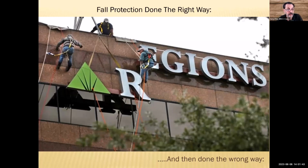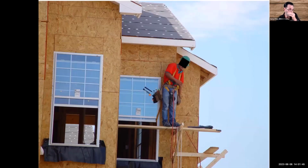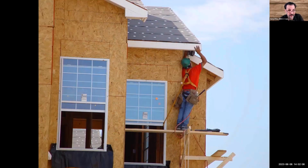But anyways, here, this is a much worse situation. He is tied off, and that's better than what you sometimes have on residential sites. But of course, his plank scaffolding system, OSHA would freak out about. But you see what he's tied off to. He's tied off to something inside the house, underneath and inside, going in that window. And this picture shows it better. That lanyard is going down instead of up above him like it should. So he's going to fall quite a ways.